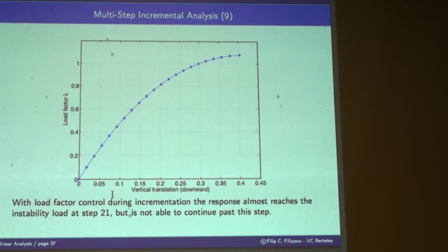So suppose I want to simulate the response of a structure that's going to come up here, come down, and snap, or soften and fade. To simulate this response, you need, as I said, to ensure that you don't apply the same load consistently. You want to have load factor control. You want to adjust the amount of load you put on the structure as a function of the softer response. To be able to do that, you need to turn on displacement control or arc length methods or some kind of adjustment of the load factor, right?